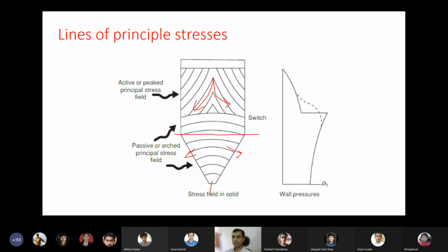As soon as you start emptying, what happens? The sigma C versus sigma 1 relationship, the flow function FFC, the flow entirely depends upon this, right?